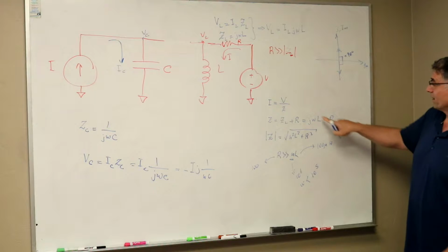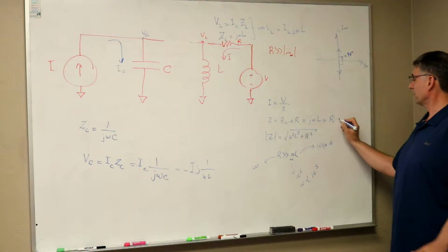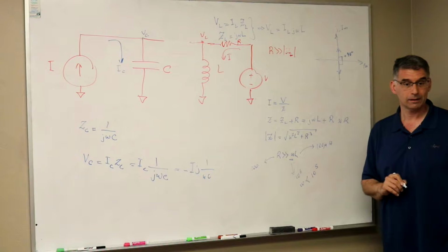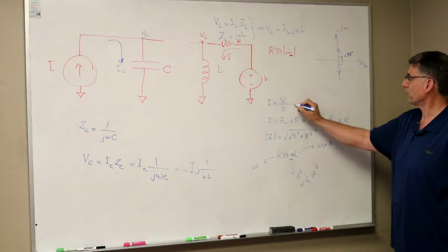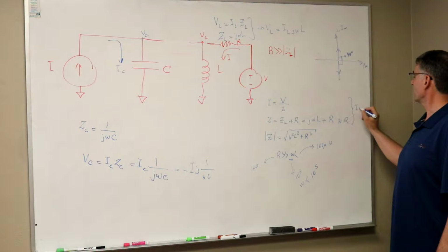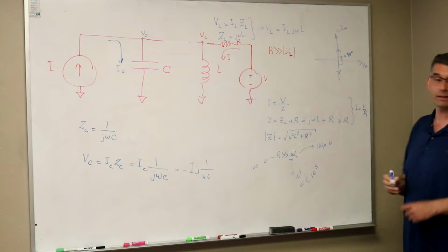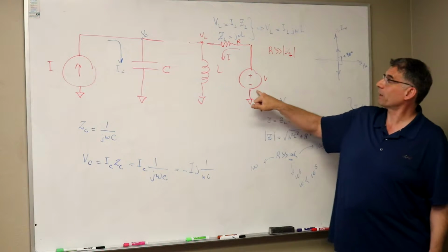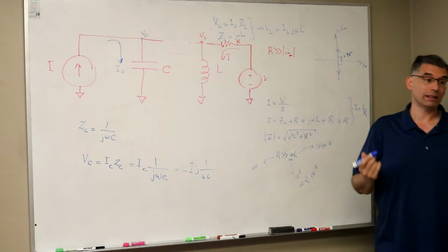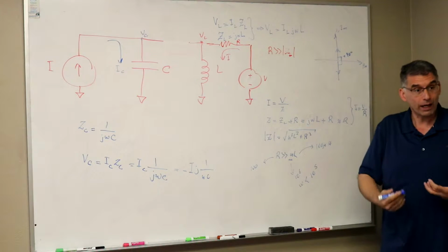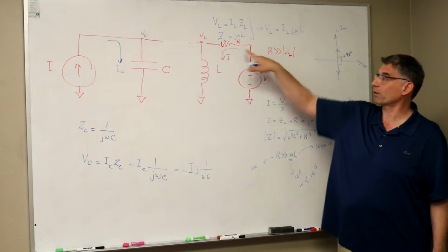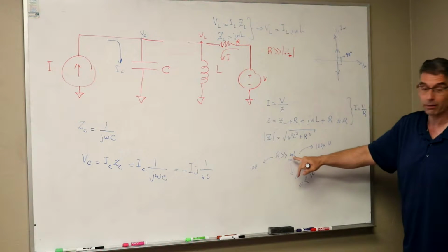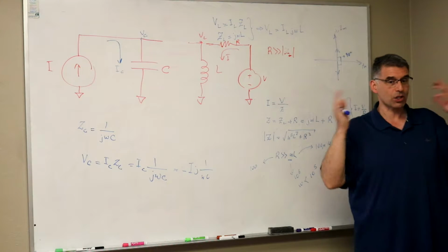So then this Z becomes approximately equal to R, right? So from there, the current just becomes V over R. Effectively, I have created from here to here a current source, where the current is defined by just V over R. Over the range of frequencies that I'm going to vary, that current is not going to change by much.